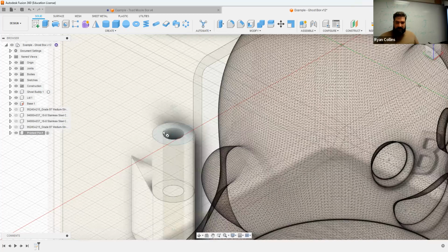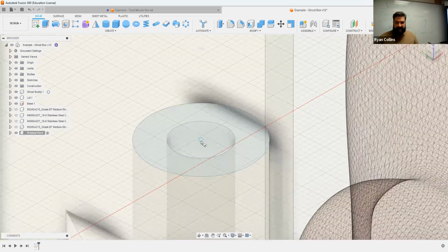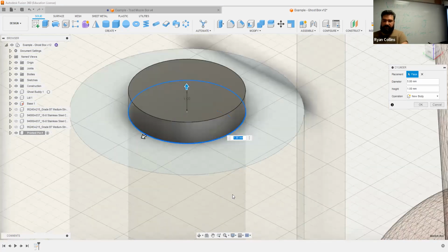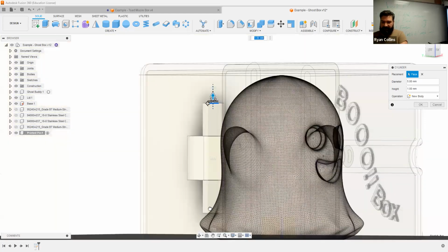And I'm going to make a center point floating over that cylinder. You see how as I mouse over, the little circle tool pops up? That is the constraint symbol for concentric. That means it's going to put it right smack in the middle of this circle. There we go. So make that 5 millimeters. And there we go. Enter. And I want to make sure to extrude this all the way through. So we know that's 50. So let's make it a little bit longer. Let's make it, I don't know, 55. Negative 55. Goes all the way down.